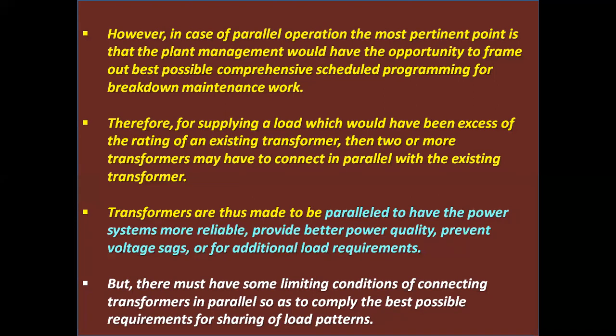Transformers are thus paralleled to make the power systems more reliable, provide better power quality, prevent voltage sags, or meet additional load requirements. But there must be some limiting conditions for connecting transformers in parallel so as to comply with the best possible requirements for sharing of load patterns.